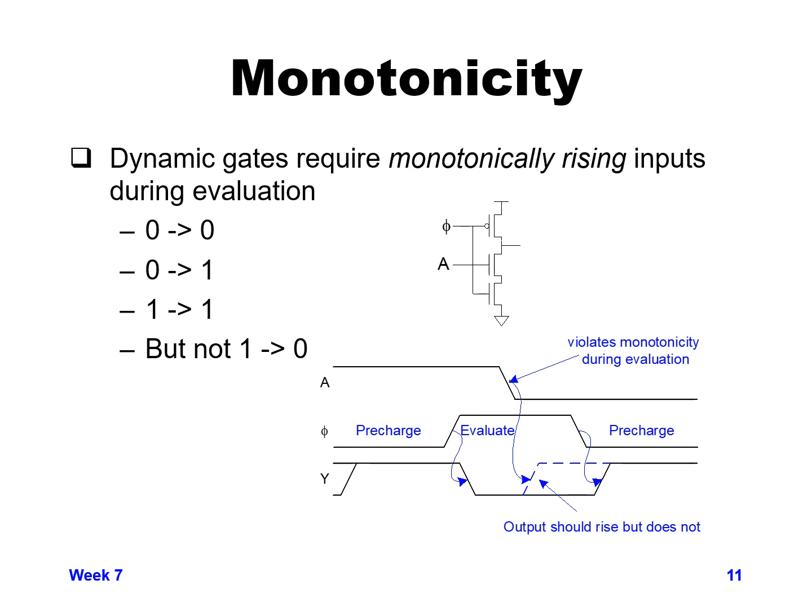If A is 1 and your clock goes from pre-charge to evaluate, the value of A being high will cause your output to switch from high to low as soon as the clock goes from pre-charge to evaluate.